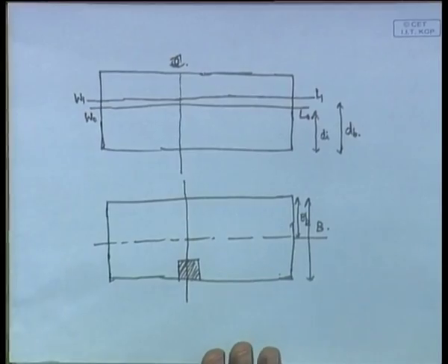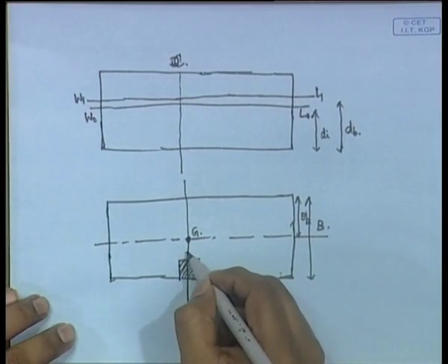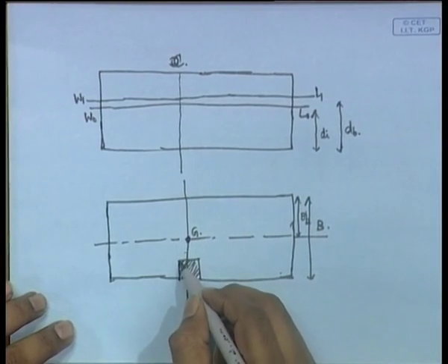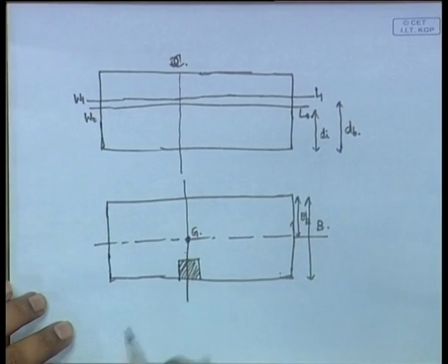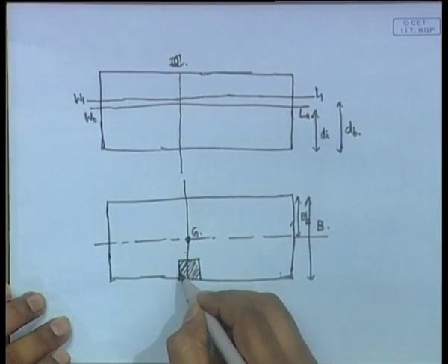This problem is all very simple. We are doing all of this for box shaped vessels, such that your G, B, everything is very simple. You can directly calculate it from rectangle, square, all those kinds of volumes. So, the G of this vessel, since it is a perfect rectangle, will be at the center here. But now this region gets bilged, G will not change. Remember, I have already said that G does not change in any of these problems. In bilging, we do not change G at all, but your B is changing.